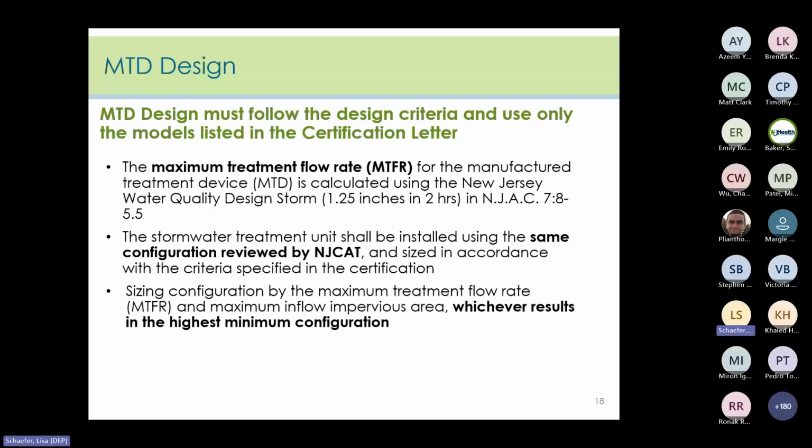So because only specific MTD models from the MTD manufacturer were tested, the manufacturer's other models that are not listed in the certification letter, even though they're the same type, cannot be used to meet the water quality design and performance standards. Also, the MTDs were tested under specific configurations and installation specifications. So MTDs that deviate from the configuration or installation specifications cannot be used to meet the water quality design and performance standards.